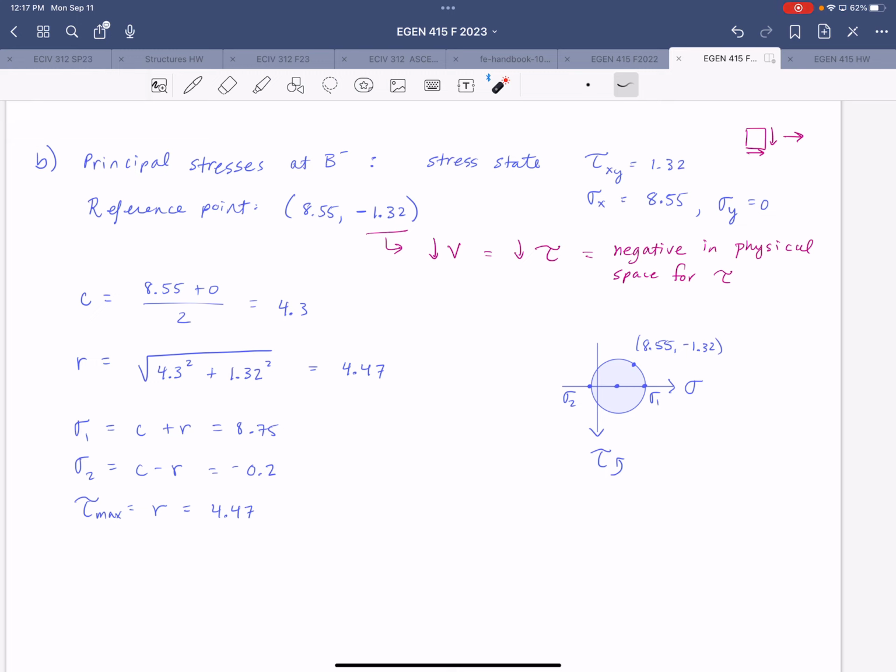If you use the top face, for example, you just have to think about that shear stress sign convention a little bit more. So if you already did your homework 3 and you decided to use the top face instead of the right face and you missed that point, and you got the sign convention wrong on Mohr's circle, that's okay, you won't lose points for that. I'm guessing everybody probably just used the right face though. But it was worth clarifying that in this lecture, right? Any questions?